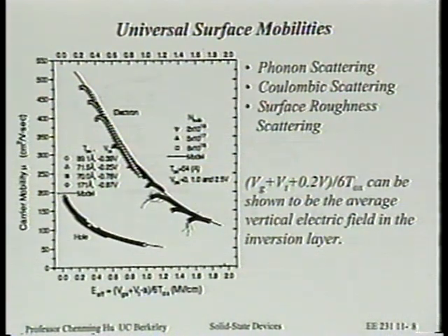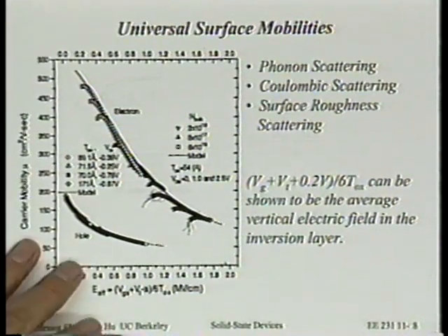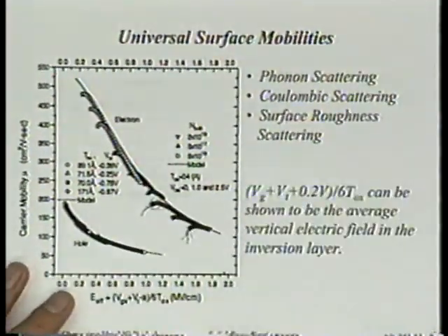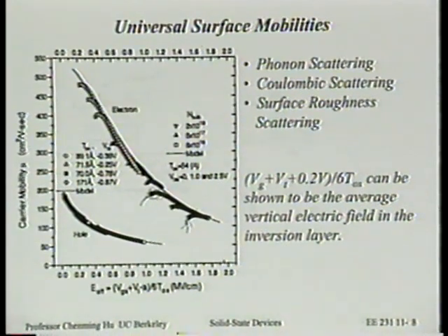Is that right? Okay. We don't know why that's the case. Now back to the case of PMOS versus NMOS. What might be the difference of the noise? I don't know the answer to that. But just like I said, mobility can be a function of vertical field. In other words, even though both transistors are surface transistors, just because one does not push the electron as close to the surface could give us better mobility.